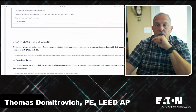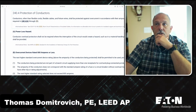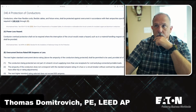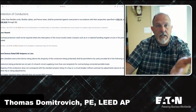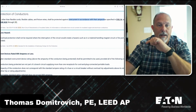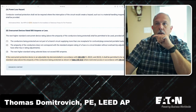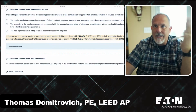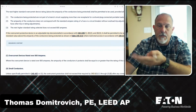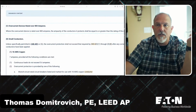Now let's talk about overcurrent protection of a conductor. Conductors, other than flexible cords, flexible cables, and fixture wires, have to be protected against overcurrent in accordance with their ampacities. So we know that. And we know that you can go to the next higher when you're protecting a conductor. We already talked about that. Where the overcurrent device is rated over 800 amps, you can't go, blah, blah, blah.